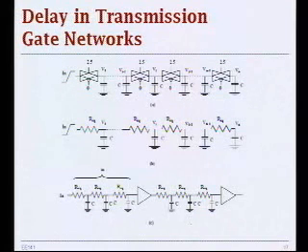And how do we linearize that delay? How do we make that delay as close to linear as possible? What did we do for wires? We know for wires, the delay is proportional to what? The length squared. And how did we try to linearize a wire?